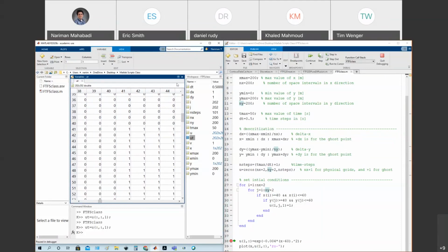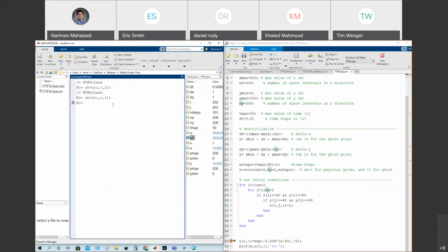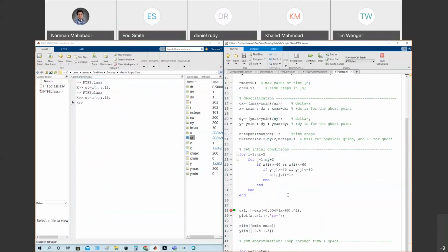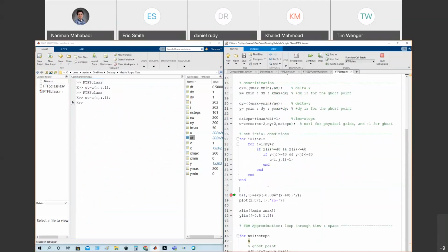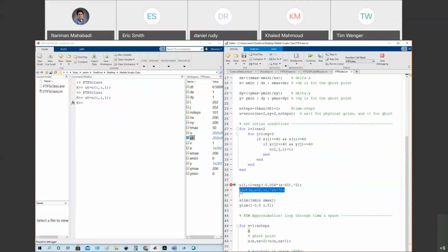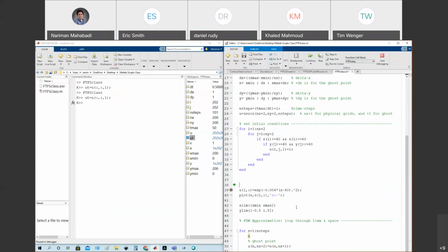It's not very efficient, so I'm going to show you how you can see this through a contour plot. For a 1D problem, we could plot this in terms of a curve, right? In this case, it's not doable. It's a two-dimensional problem. So let's plot this in terms of a contour. And this is the script that you can use in MATLAB. Contour. And I'm going to plot my unknown function for all the unknowns on x and y, but for just the time interval of 1.